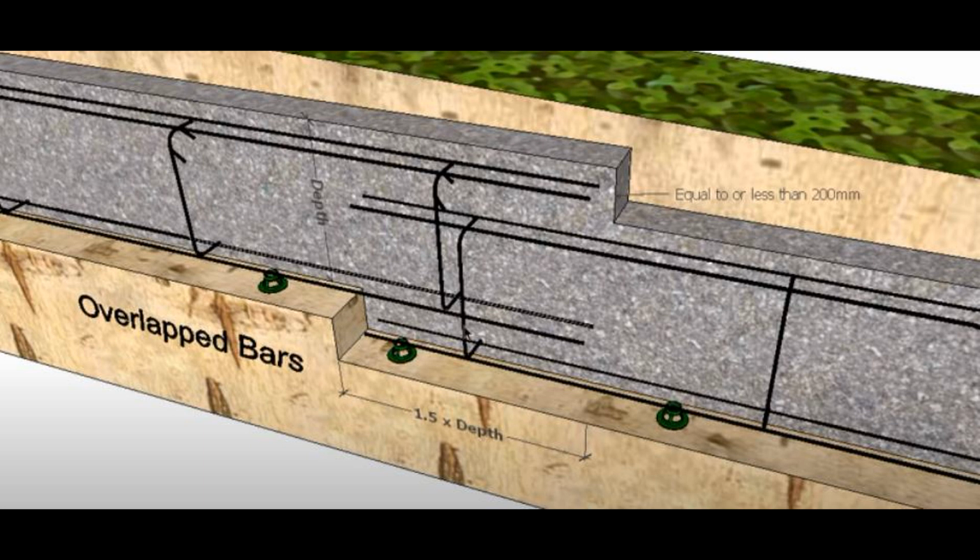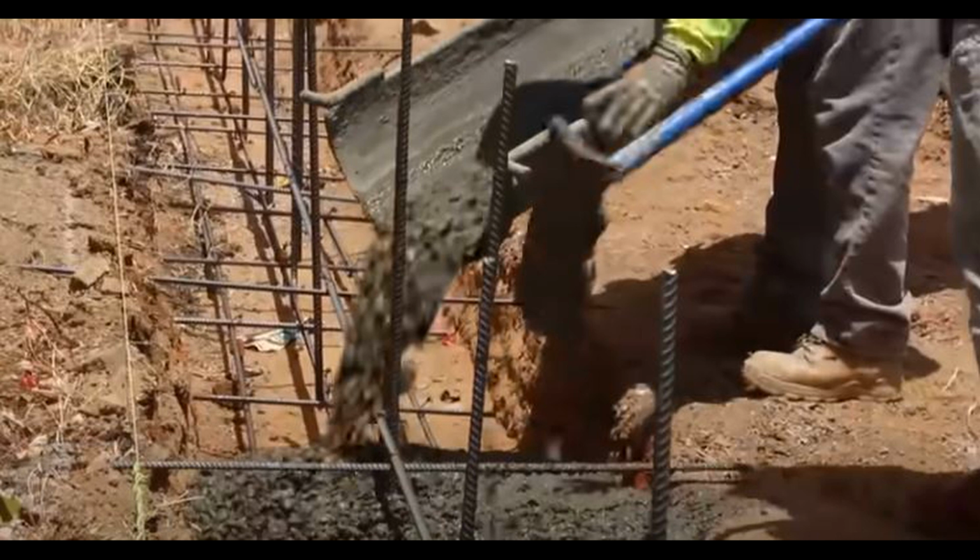During concrete work at the footing, it needs to be ensured that the minimum strength of the concrete shall be 32 megapascal, which requires a slump of about 100 millimeter, and the maximum aggregate size shall be 20 millimeter. Concrete is required to be compacted using a mechanical vibrator.